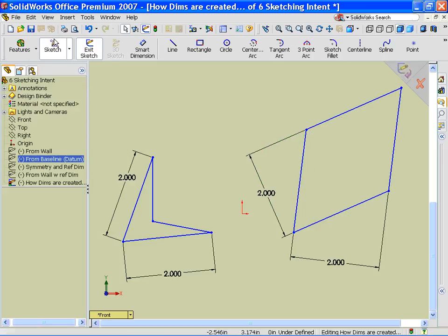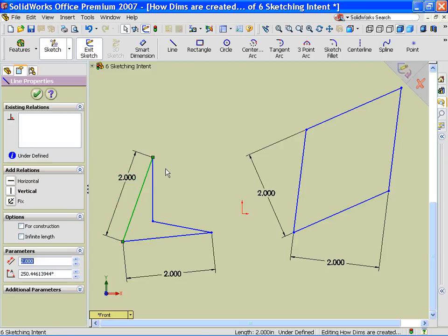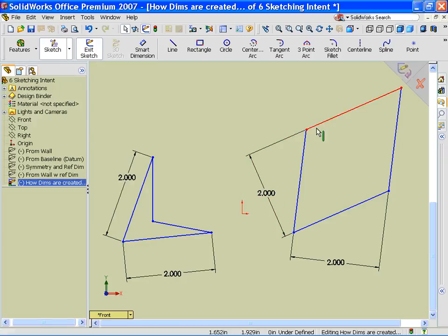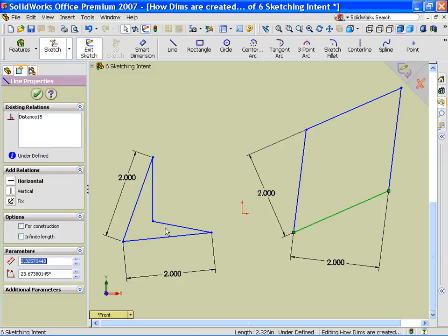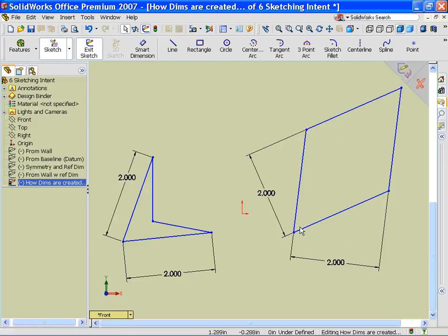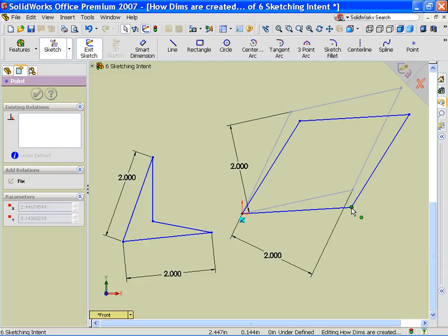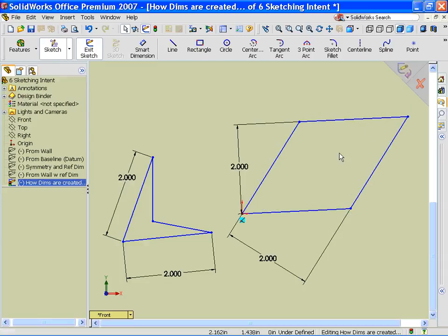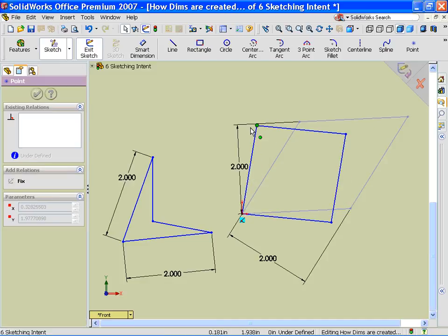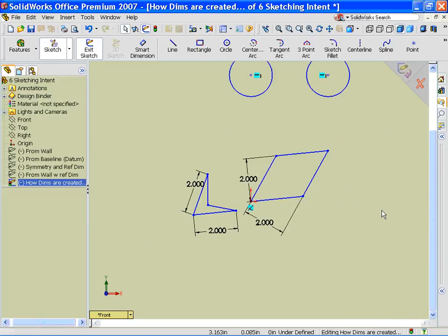See, what's actually going on in these scenarios is that over here, it's maintaining the distance of that edge. Or here, it's maintaining the point-to-point distance. Over here, we asked for edge to edge. Likewise here, edge to edge. So that's exactly what it's doing. This edge might be a little bit longer than that one, but this part will be easier to fix after stuff has gone wrong. Not to mention in the real world, since nothing is perfect, this is more accurate as far as what you're actually going to get out of a machine. Not everything's going to have perfect 90-degree corners anyway.